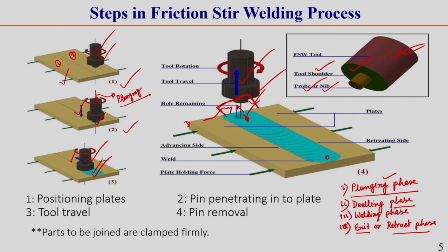It is called dummy material, or you can say some extra material. Whatever hole is created when you remove the tool from the dummy material zone stays in the dummy material. Or if you remove the tool from the workpiece material, then whatever hole is there, we can use some filler material to fill that hole.